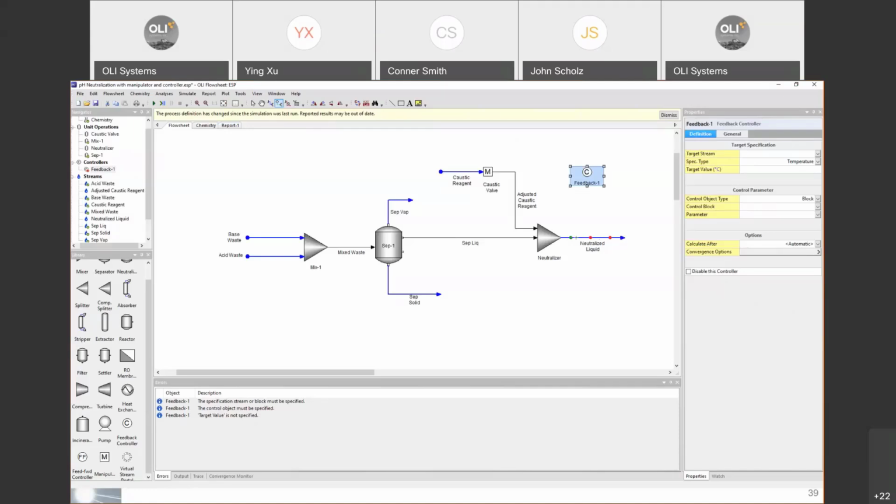You'll see that there are several connectors here, the red dots. Those are the 3 possible connections that you can do. So I'm going to select the third one. It becomes green when I am ready to do a connection. So click on it, and now drag your mouse towards the controller. The controller will also show different connector points. I'm going to select this one to the right, click on it. So you have your first connection, measured to controller.